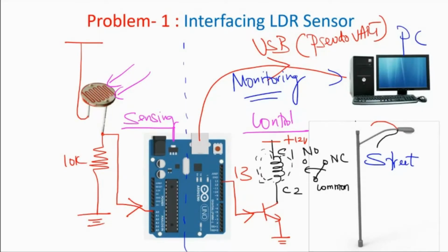So this live wire we connect it to the phase. We break this neutral wire. One point we connect it to common. Another point we take from normally open and complete the circuit. So one end of the live wire is going to phase. The neutral wire is broken and it is connected via the switch. When this switch turns on, the circuit is closed.